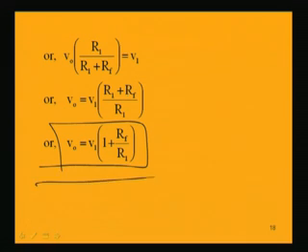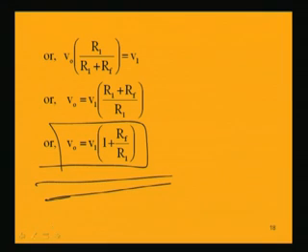So, this is also a very important example of op amp application, which is the non-inverting amplifier. Its output is given by the input voltage into (1 plus Rf by R1). So, this is for non-inverting. Earlier, minus Rf by R1 was the gain for the inverting op amp, and here the gain is 1 plus Rf by R1.